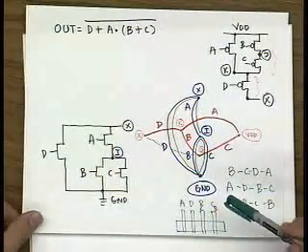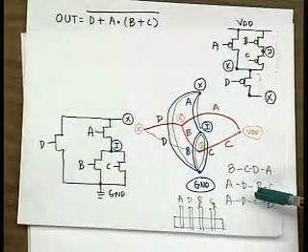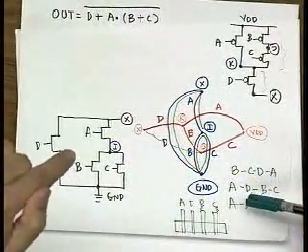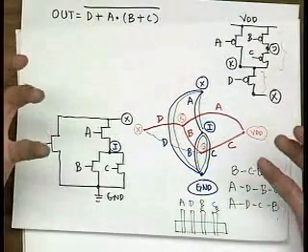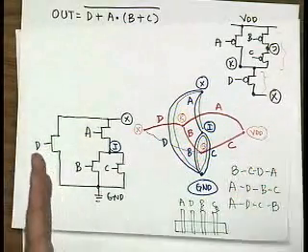So now that you understand the Euler path, the next step is to find the Euler path with the same sequence in the pull-up network. If you're able to identify Euler paths in the pull-up and pull-down networks, this means you will have the same sequence of gate signals.